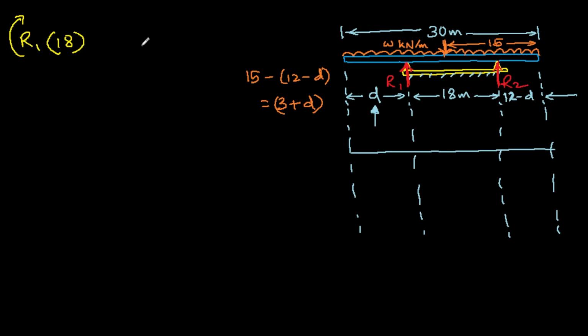Yeah, so then that is equal to the counterclockwise moment, 30 meters times w, the total weight, acting at a distance of 3 plus d.